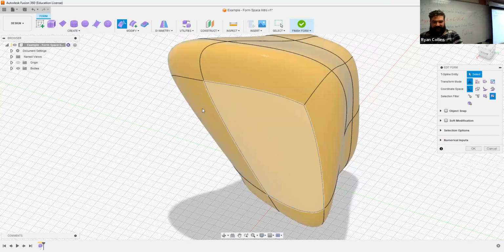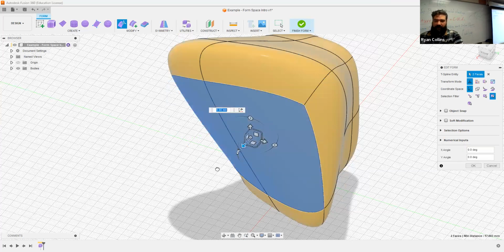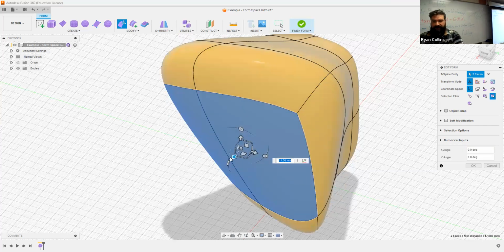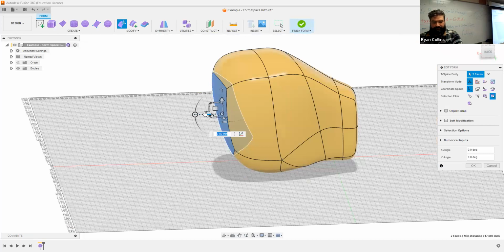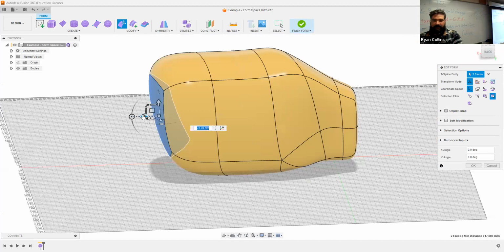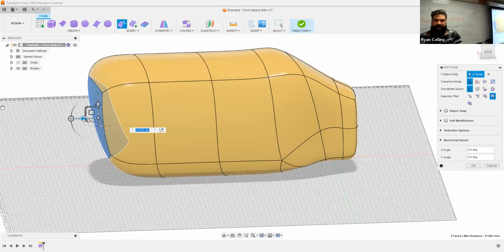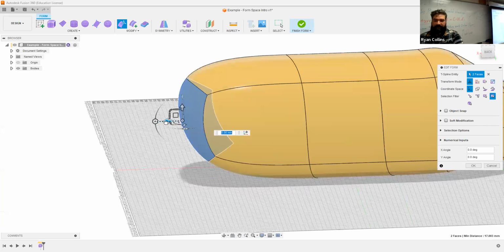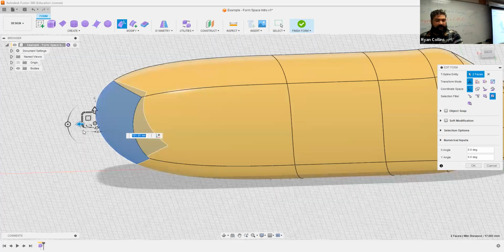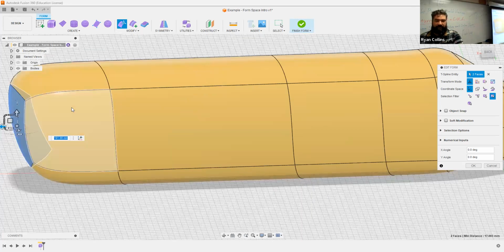So things like if I select a couple faces, I can drag outward. But if you press and hold Alt, it actually extrudes. It's a soft extrude, not a direct extrude. Press and hold Alt, now move. See how it's actually adding lines? Without pressing and holding, it just stretches it, making an extra long Twinkie. But see, it's not adding any faces or anything like that. When I press and hold Alt, it actually creates a new edge there and then moves outward.